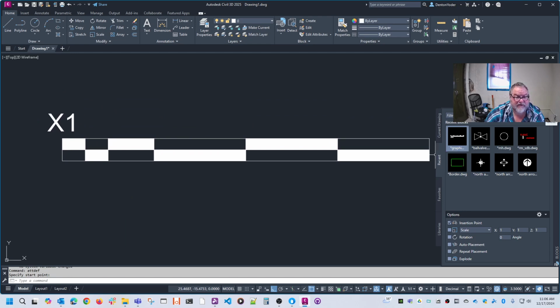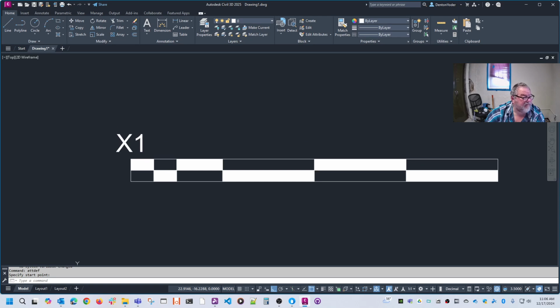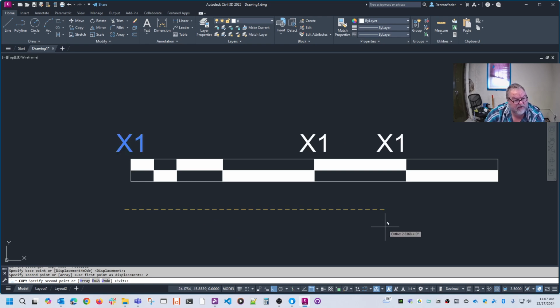and put it just up above that starting line, and it jumped to center justified. Let me close this window so I have more screen space. So that is an attribute that I defined, ATTDEF. The nice thing is, I can copy it for the others. So I can do a copy this, and I want to copy it over directly 2 inches, 3 inches, and 4 inches.